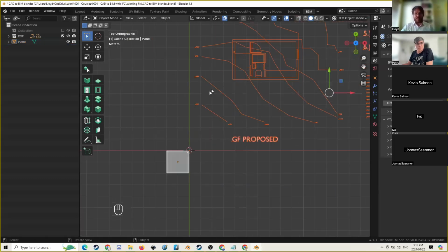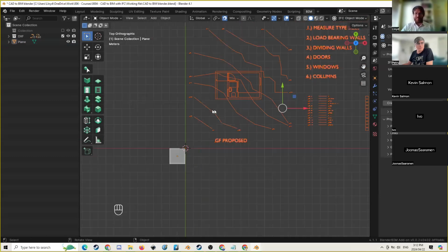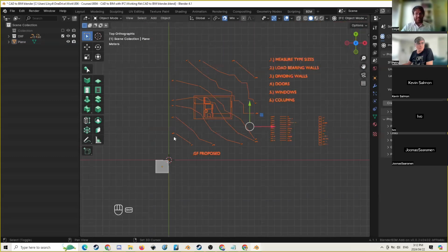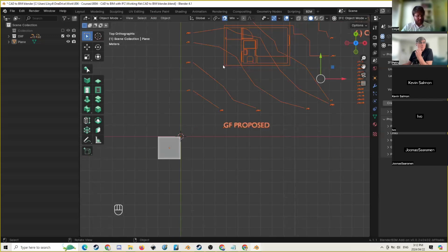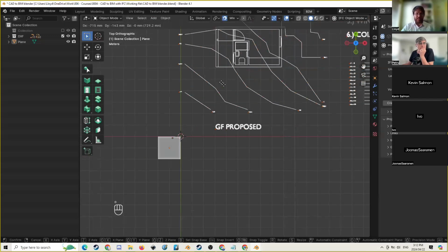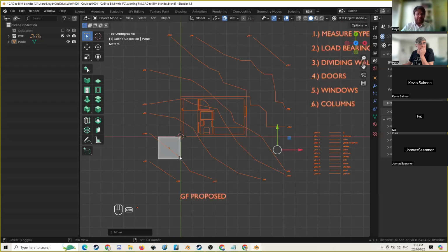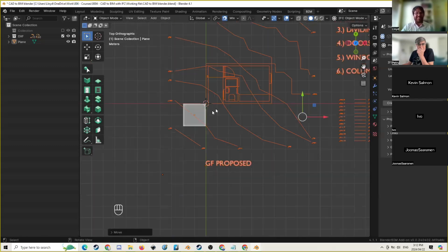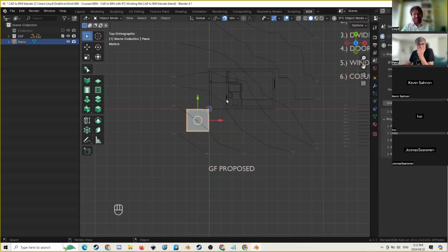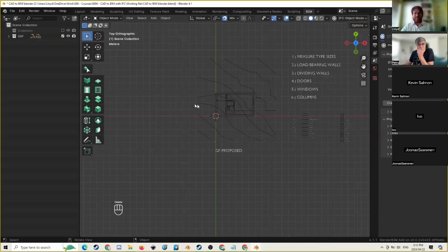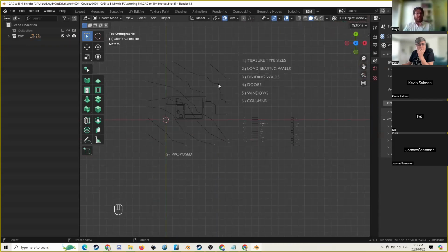And then I'm just going to grab all those curves here, which came in through the DXF, and I'm going to move it to align this corner. So I'm just going to press G, which is grab. I'm going to press B, to select a base point. So this allows me to snap and then snap it to that origin center. This just helps me get a clean file. It just works better with my brain. And then I'm going to delete this reference. So this is here, and it's all set up how I want it to be.